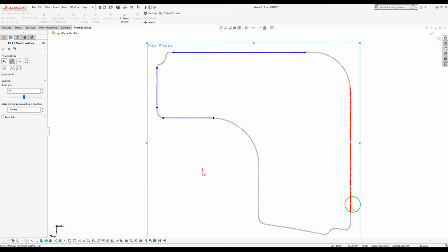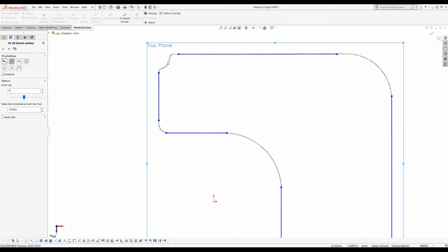Normally you should have a strategy for the fillets: leave them, don't create them now, but leave the software to actually interpolate and create them the way you want. For example, here I have an arc that I will need to fill it later, so I'll just take and mark this to be my arc.